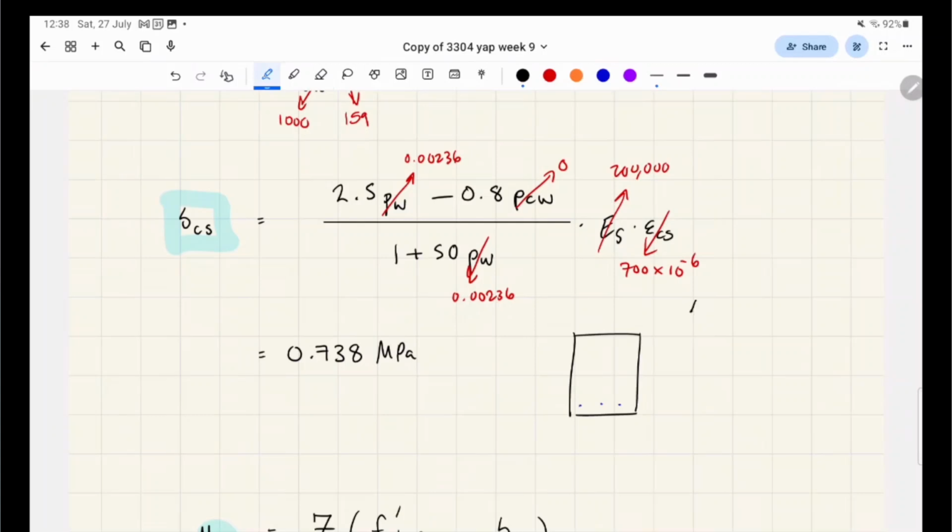let me draw this. Here's our stress distribution. It looks like that, because remember how we said the neutral axis will probably be bottom weighted? This is for a beam, for example. Which side will it crack from? Are you sure? Bottom. Why the bottom? It's in tension. And concrete's weaker in tension. Perfect. So this is where the concrete's going to start to crack.